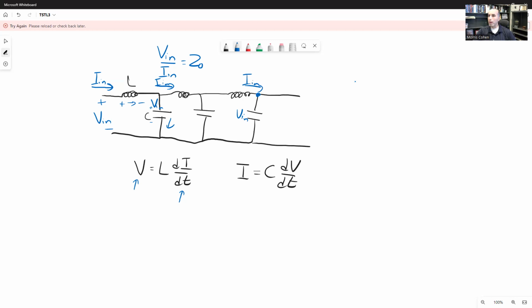All right, but here we got a problem, because there's nothing else. There is no next capacitor where this can appear. So you've got this voltage sitting right here. And so what is going to happen, right? Think about this for a second, then I'll try to walk you through this situation. You've got this voltage across this inductor, you've got this current going through, and nothing at the next branch. All right. So think about this if you want, pause the video, but let me give you a little bit